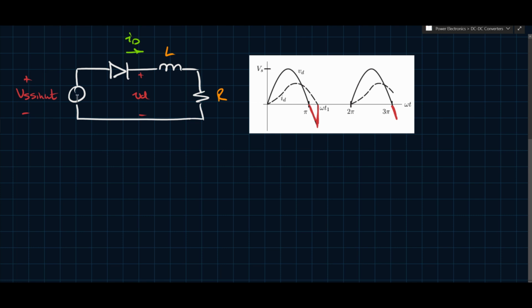And in reality, we know that a voltage source is not ideal, and usually there is some type of series inductor with the voltage source, which has to do with the internal magnetics. If it's coming from a source that's like a power system, that might have to do with the actual inductance of the system, but there's always some equivalent inductance in series with these voltage sources. So this is a more practical circuit than the purely resistive circuit that we saw in the previous case.